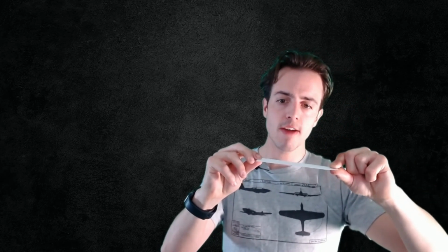Now, if I have large wing aft sweep, then an increase in bending presents the upper side of the wing to the flow, which is a reduction in angle of attack. If I've got an unswept wing, bending doesn't change the angle of attack at all. If we have forward sweep, then an increase in bending presents the lower surface to the flow, i.e. it increases the angle of attack.